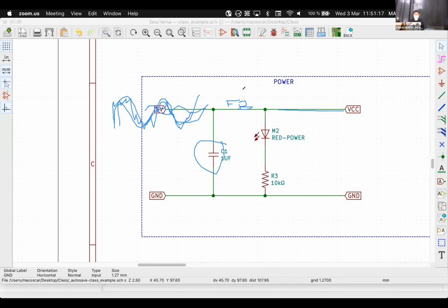You will see this in more advanced electronics that have very low noise requirements that are able to clean both. High frequency with the ferrite, which goes in series, and low frequency with the capacitor, but mostly it's for cleaning noise. Interference normally is not done with a capacitor, but it's done with either Faraday cages or with big ground plates that make shields, let's say, that absorb that interference so it doesn't go into the wire, okay?